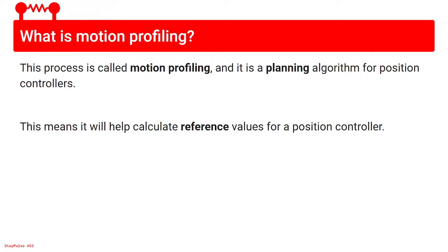You said you plug your voltage values back into your PID, combining PID and feed forward. You just add them together. I had a question: for PID, both the set point and the measurement have to be the same exact units, right? So the measurement PID takes in would not be a speed. For position it would be position and position, and then the feed forward. But since it's taking in the output of the feed forward, it has to be voltage. It's not taking in the output. You're just adding them together.